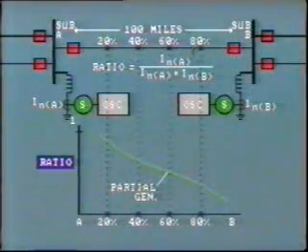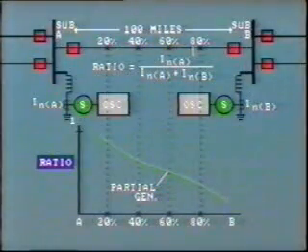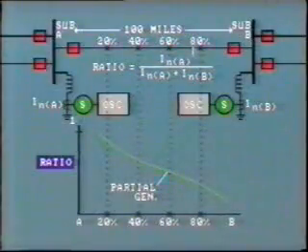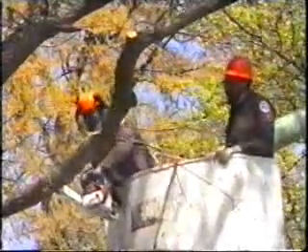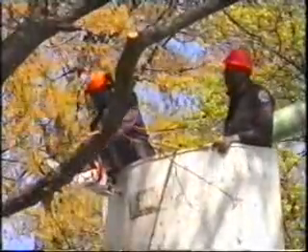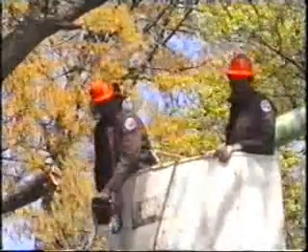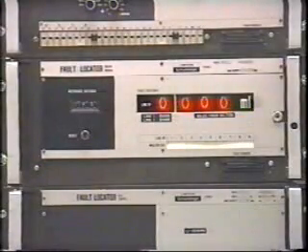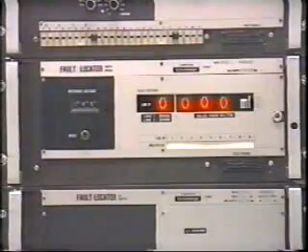In this particular case, a foot patrol located the probable tree contact within a mile of the calculated distance. The problem of recurring tripping of the line was solved by tree trimming. Incidentally, some utilities use fault locators which are programmed to perform the calculations and then give us the exact distance to the fault.